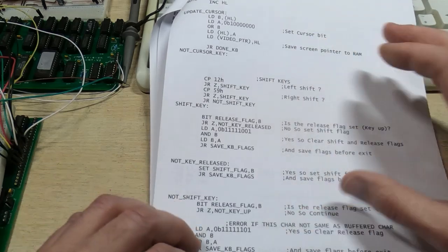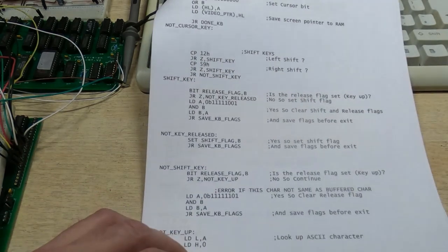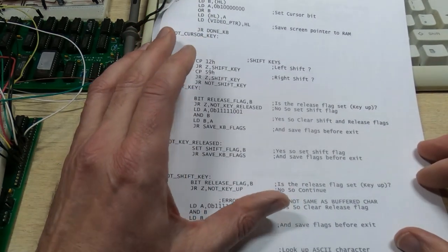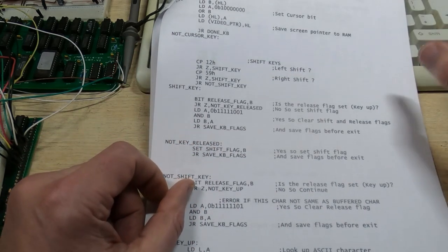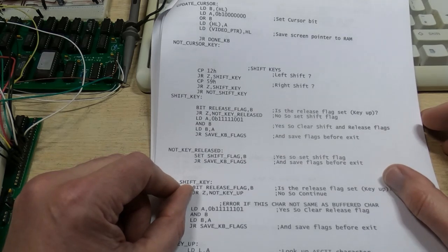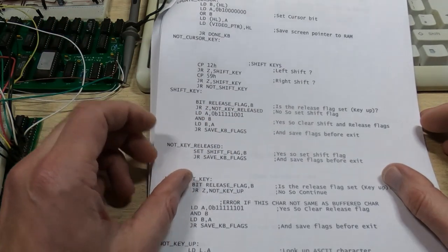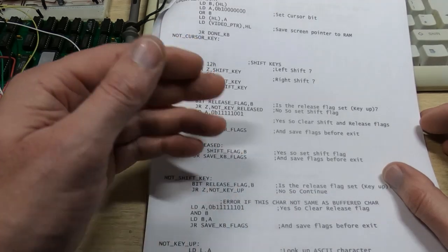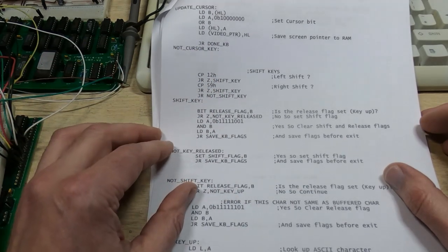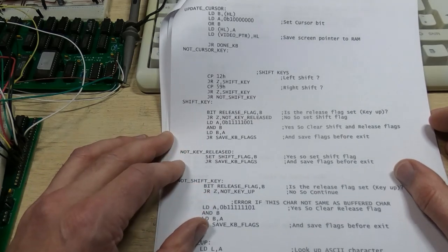We can have what amounts to a 2.5 page interrupt handler that does the conversion of the character from the PS2 keyboard into ASCII. It deals with the cursor movement and it deals with shifting of the keys and selecting the appropriate conversion based on whether we're in shift mode or standard mode.